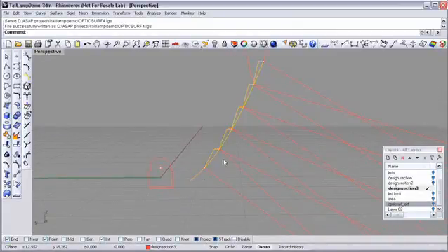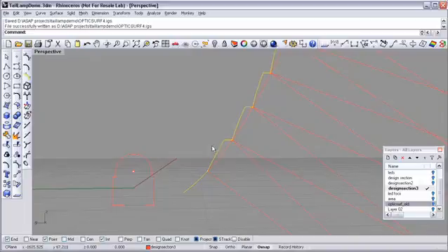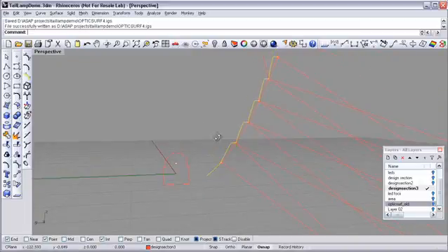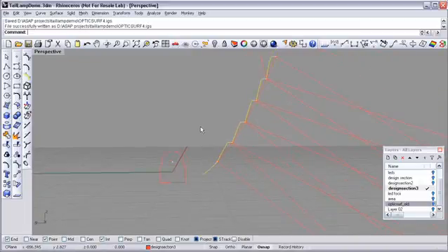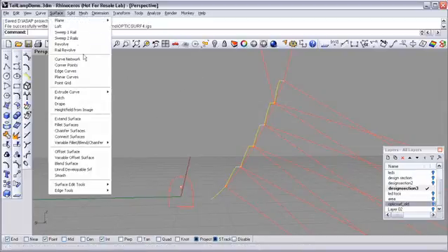Again, we have our base parabolic curve that we were working on, and then I've reconstructed the segments to direct the light. In this case, putting a little bit more left-right spread so you can see the surfaces have been tipped a little bit. And the process to check this one again would be the same as we followed before.